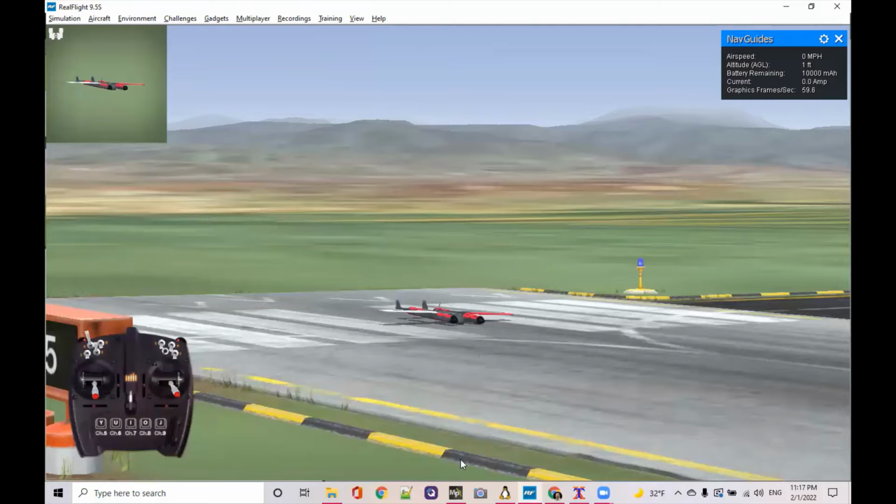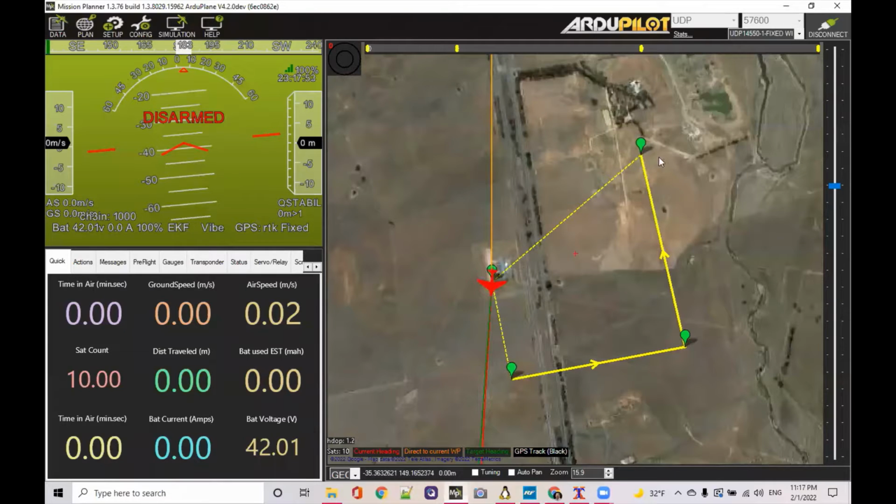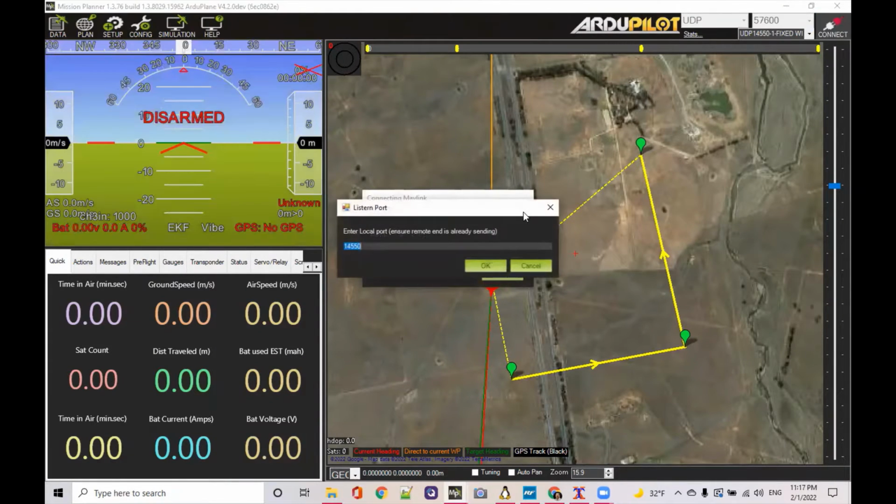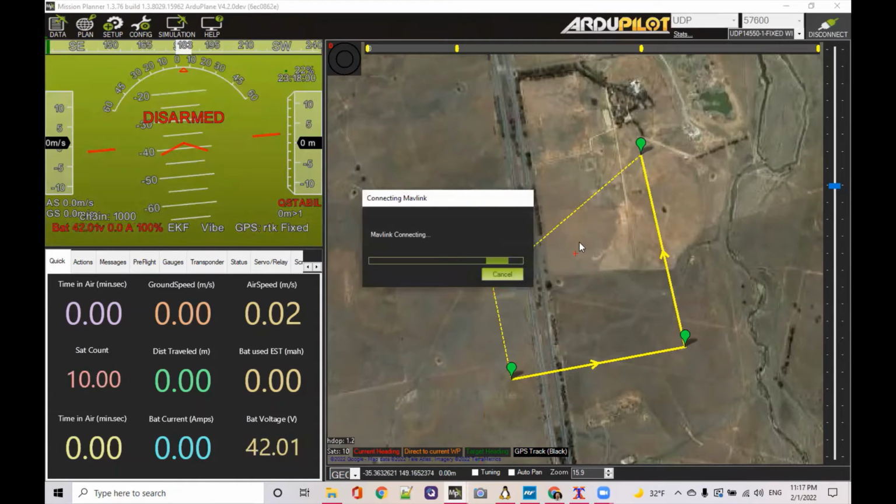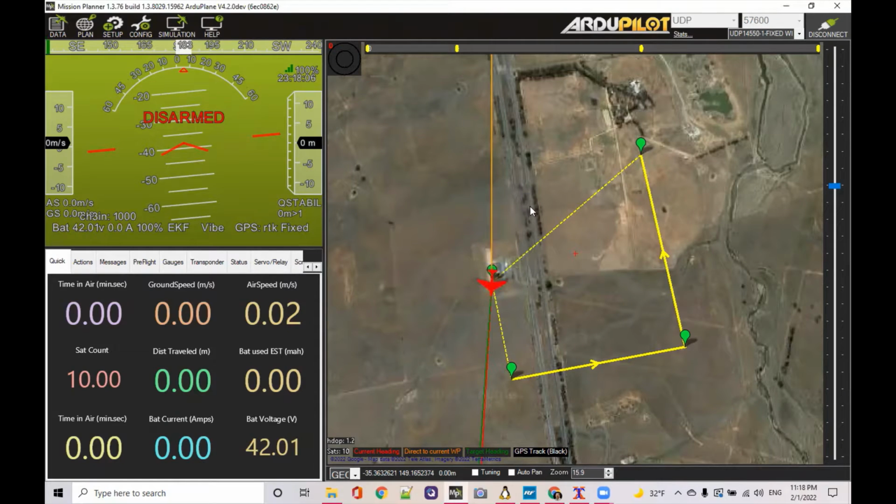And what we're going to do is connect to the vehicle, load a mission, and then execute the mission in full MDAR configuration. The first thing I'm going to do is double check the connection to the vehicle from within Mission Planner. We specify the mode change to stabilize, and we specify heading to waypoint 1. The baud speed, etc. Okay, so it's loaded.